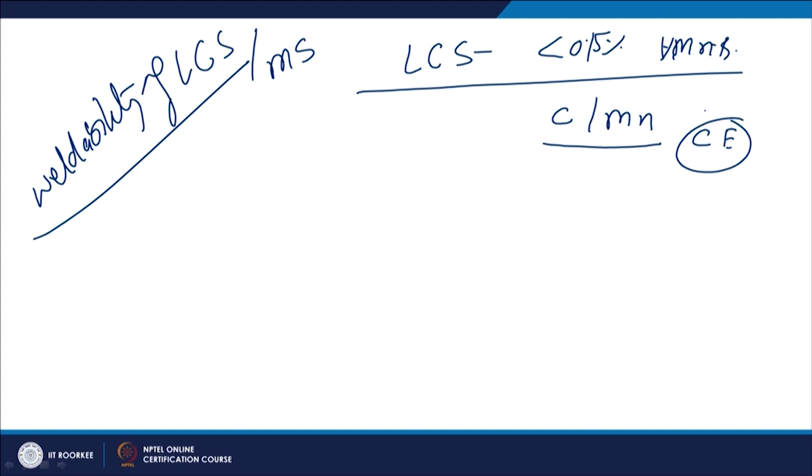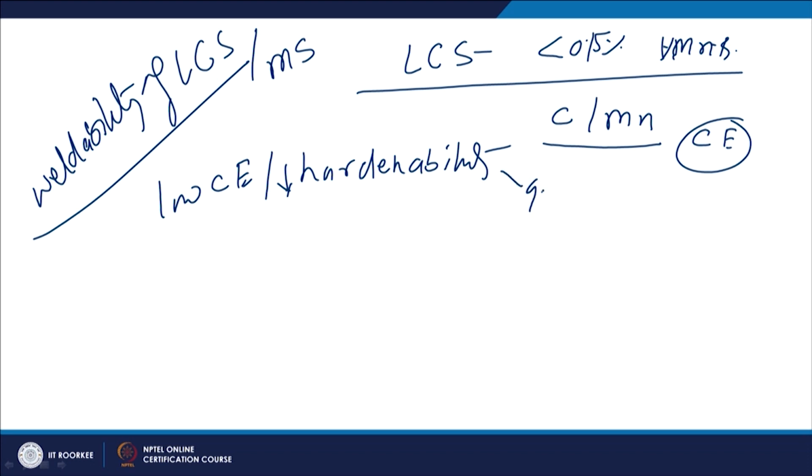So, due to the low carbon equivalent, this type of the steels offer the low hardenability, and the reduced hardenability associated with these leads to the very good weldability,